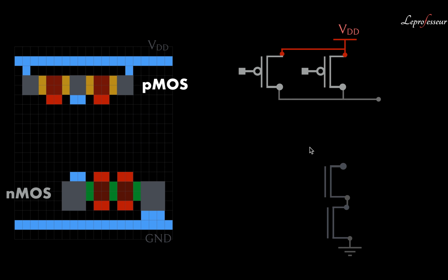Now let's draw the NMOS in series. Similarly, we could draw NMOS contact and two contacts, polysilicon layer making the gate. Okay, red polysilicon layer representing the gate. Now notice here that when we are doing in series, we do not have any contact in between. If we put a contact here in between these two red color rectangles on green line, that will make it parallel. So we are not making it parallel here. This is a series. In PMOS we made it parallel. This was a contact in between two red polysilicon layer lines.